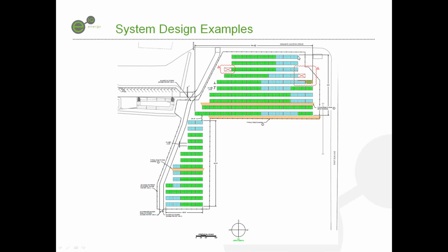So there's going to be some voltage drop there. And if the voltage drop, let's say, is 10 volts, what that's going to mean is that this vBoost unit out here is going to be needing to put at least 340 volts onto the bus for the inverter to see 330. And that happens automatically within the vBoost architecture because there is no regulation at the vBoost. It simply boosts the voltage to the point where power flows from it to the inverter. And it's kind of the simple magic, simple elegance of the solution, if you will, to allow power to constantly always flow from the source to the sink, of course the sink being the inverter.